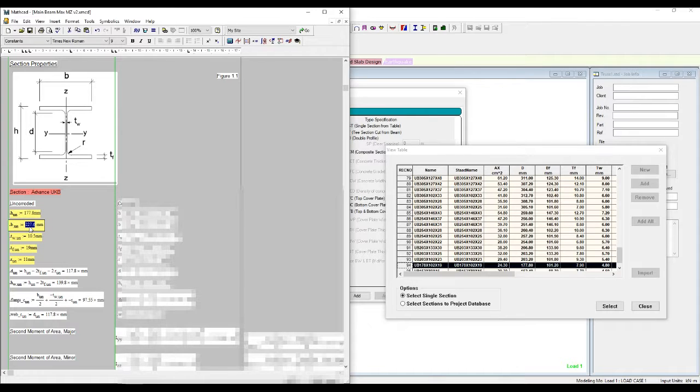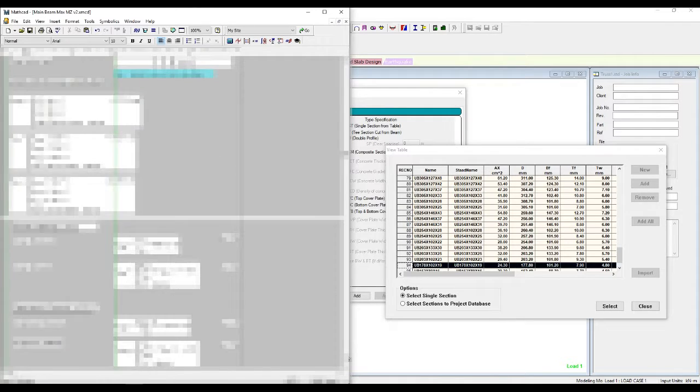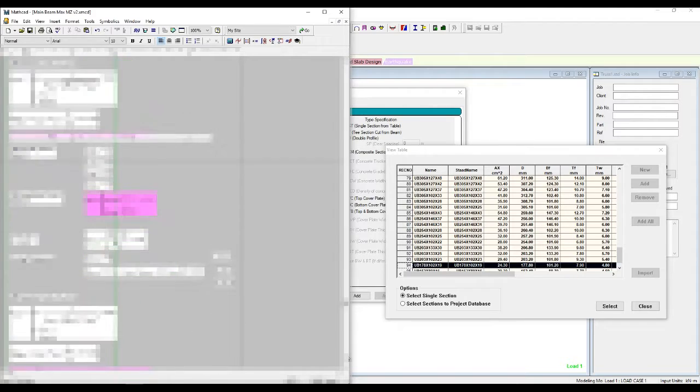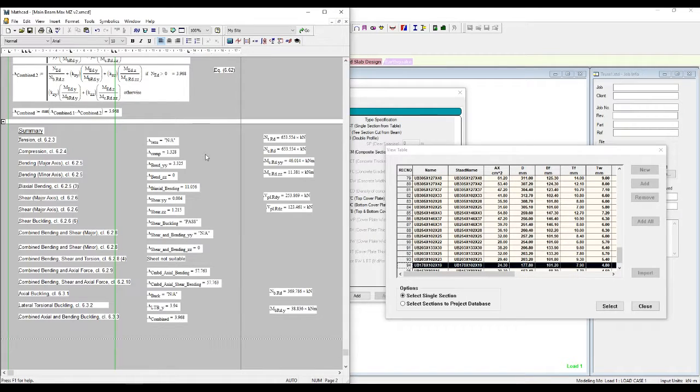that's the height of the beam, then the width, the thickness of the web is 4.8, but you can already tell that 4.8 millimeters is not a lot by the moment that I'm applying there. So this is gonna fail in so many places. So if I do this, I'm obtaining utilization ratios. In particular, the worst one is the combined shear, bending and axial force of 57. So yeah, it is bad. It's pretty bad, as everyone could understand.